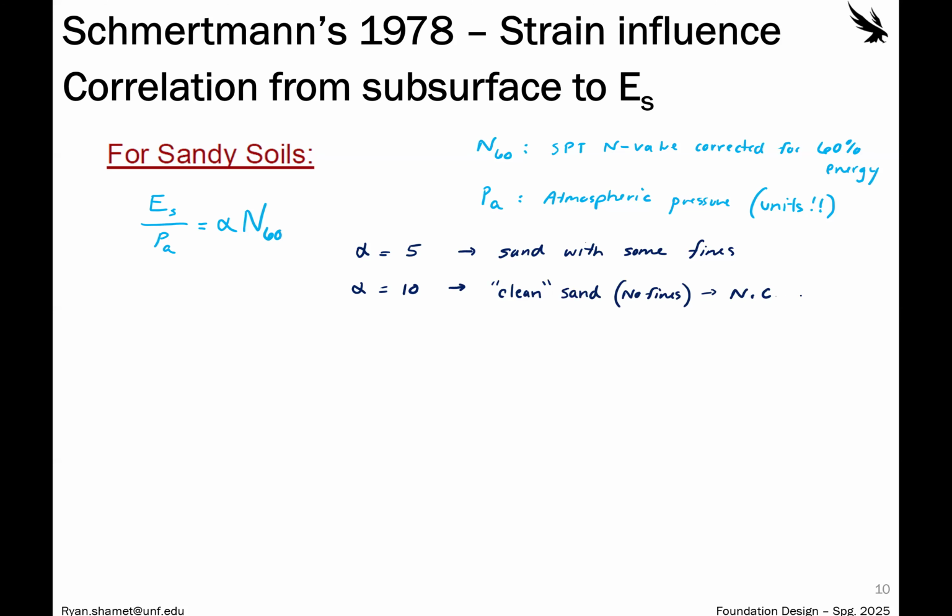This is a hard thing to think of because we don't do a consolidation test on sands. Basically, we're thinking about the geology of the region, like, was this sand under a lot of weight on top of it? It's more assumed than tested. We don't do consolidation tests or find pre-consolidation pressure of sands, all that stuff.